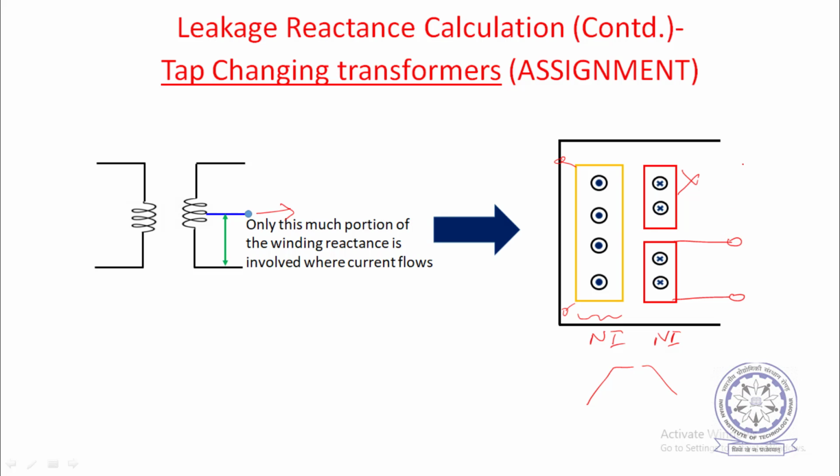But in the radial direction, here there is no MMF. So this winding you can ignore. Only one direction you have. Until this point, the MMF will simply grow linearly. And here these two are at the same height, therefore at this position it has to become 0. So here the negative slope will start, maybe much steeper, and then become 0 here. This is of more width, and this is of less width, of course. This is how the MMF wave will be. So we can calculate and find out the energy stored and all.